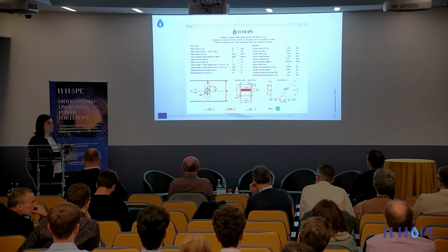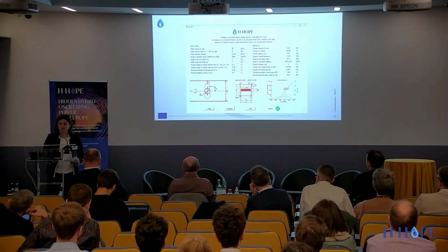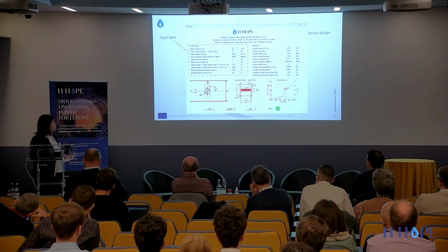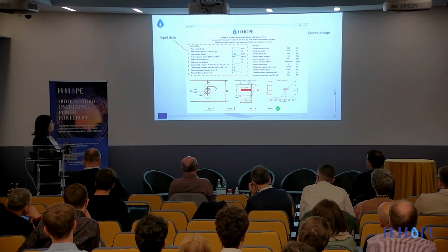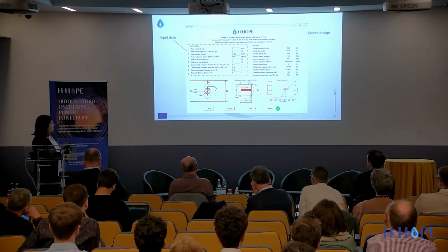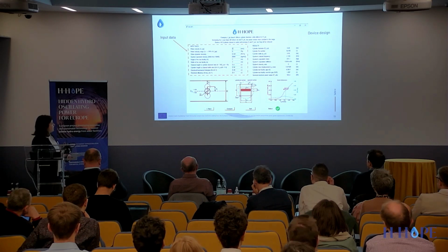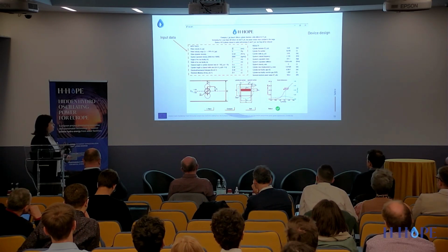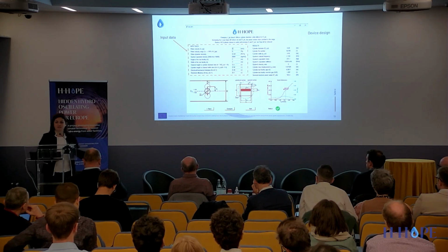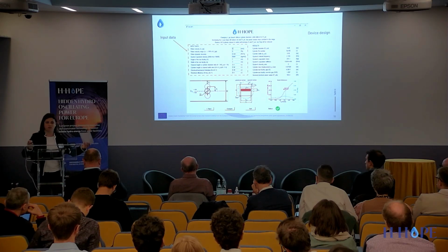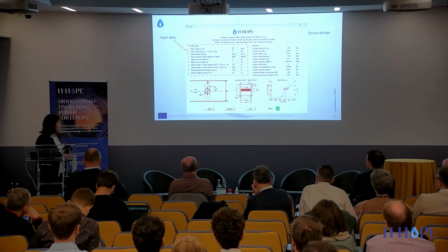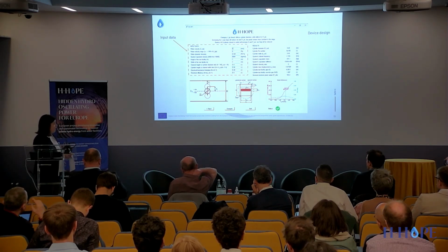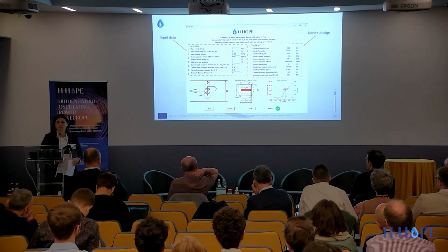And then there is a second interface in which you have to put the input data: the velocity range, the characteristics of the test facility, and some constraints related to the availability of letting the cylinder move, or if there are walls and you have to limit the movement of the cylinder itself. And then you just have to click this button, compute, and you will obtain some results.